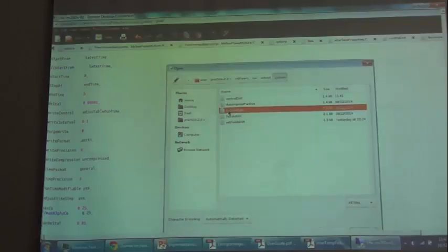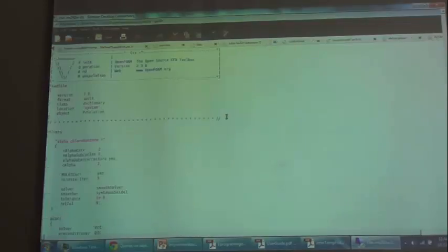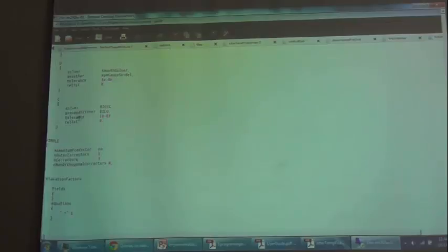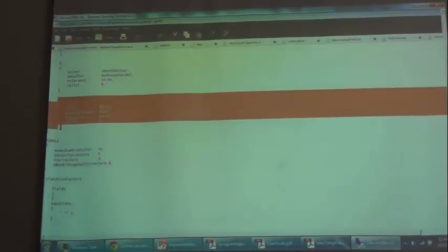Before that, coming to fvSchemes, now that we are calculating two additional divergence terms, you have to define discretization schemes for those two terms. That's being done in these two lines. This is the divergence of phi C, or divergence of U dot C, in this equation. And coming to fvSolution, everything stays the same except you have to include the methodology that we'll be using for solving the C equation.